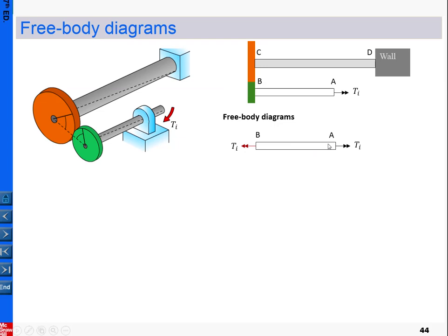So basically from here the AB shaft is under torsion. From this case, you can see the stress in AB, taking our template, is TR over J. Whatever the information regarding AB, J is the polar moment of inertia of AB, and if we are given the radius, you can calculate J. And R is the parameter. So for example, if you want to calculate the maximum stress in AB, then you simply pick the radius of the shaft AB for R.